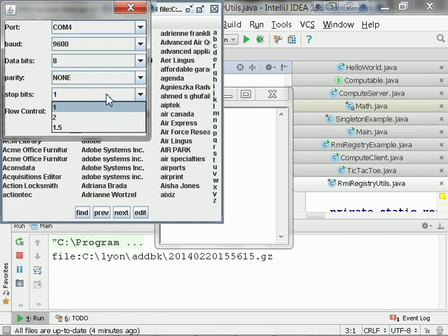Stop bits are what are called framing bits. Framing bits are involved with taking the character and putting well-known bits before and after the code word so that you can see when the code word begins and when the code word ends. Because what happens when you transmit binary data down a single wire is the on-off signals have no clock. As a result of having no clock, they are said to be asynchronous. Asynchronous means without a clock.